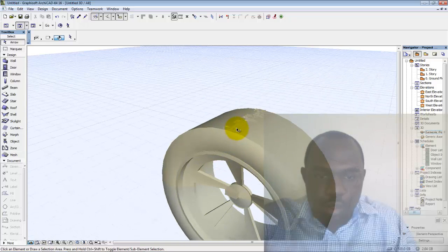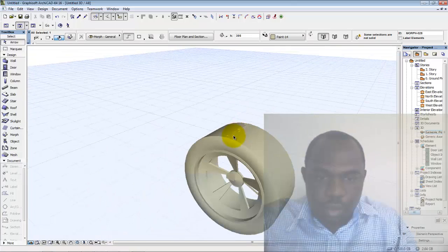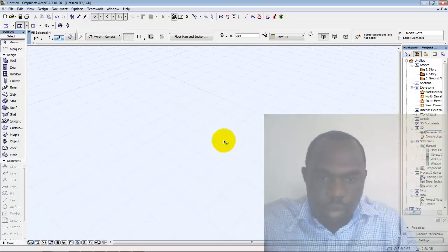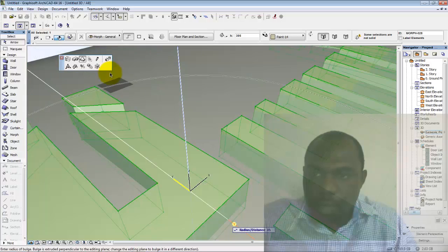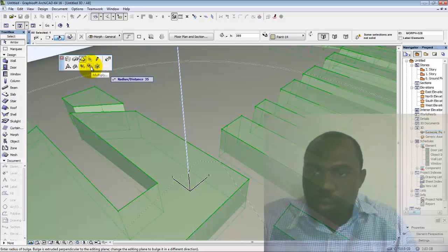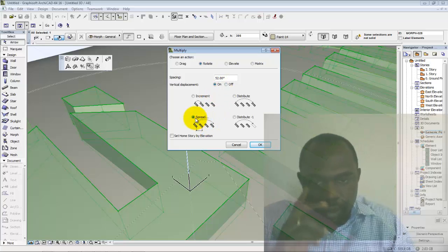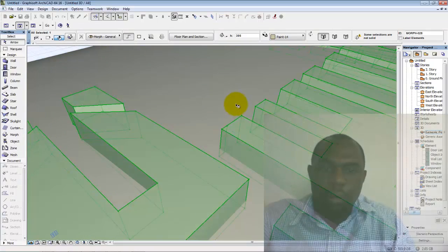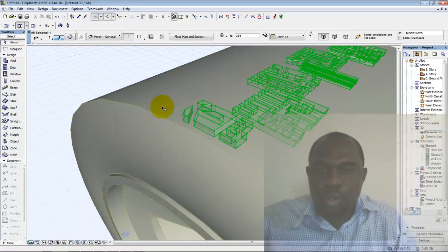After grouping them, you will now select them. So then you click a surface, any surface at all, on the grouped element. So it gives us this palette tool. So we go to multiply and make sure it's selected on thread. But before we do that, we need to know by how much we're going to turn it around.